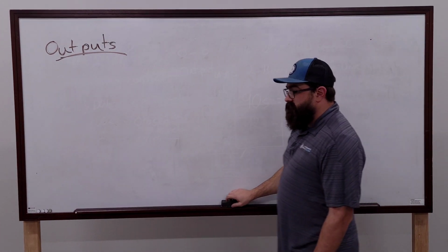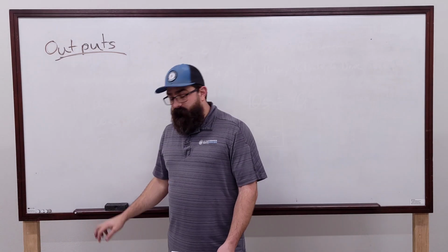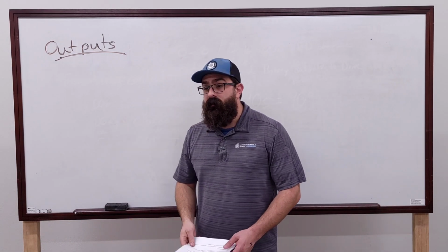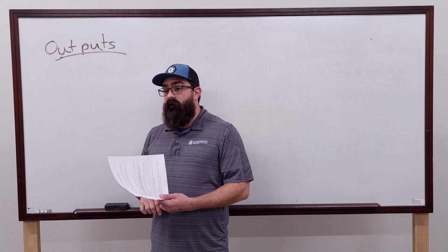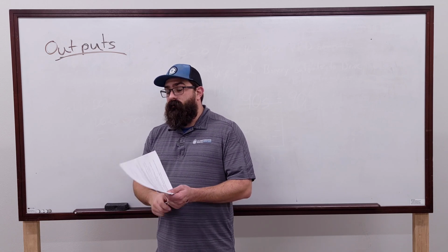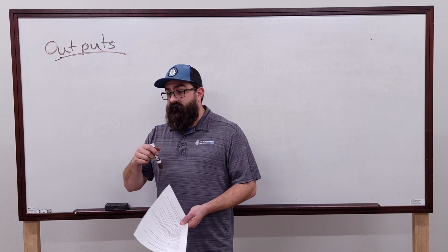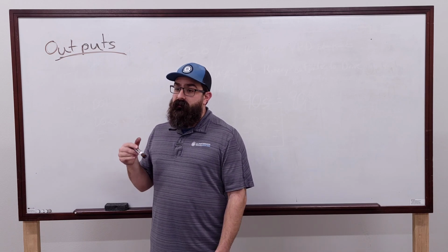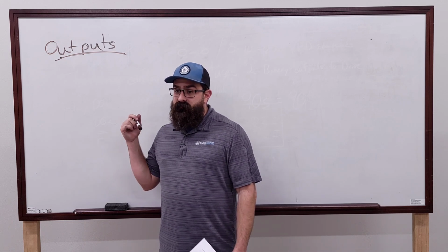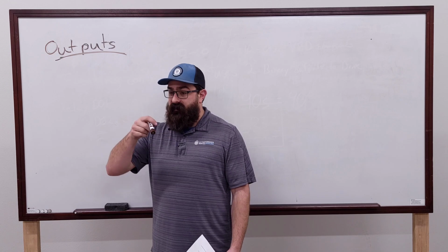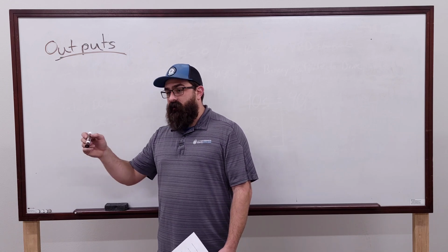Yes. So some do, some don't. Not all of them. It all depends on how it's set up. But Honeywell syncs on occupied. But you can change it. There's a check button in the logic for those actuators where I can change where it syncs: when it comes occupied, or I can sync when it goes unoccupied.